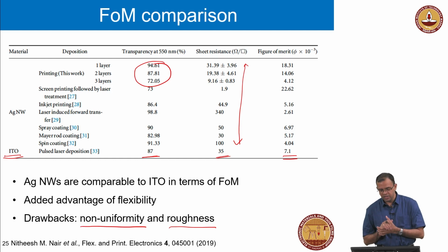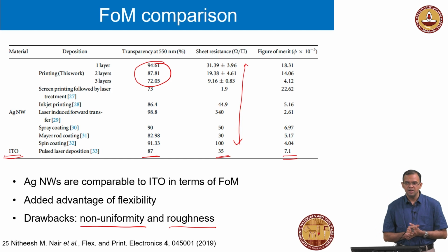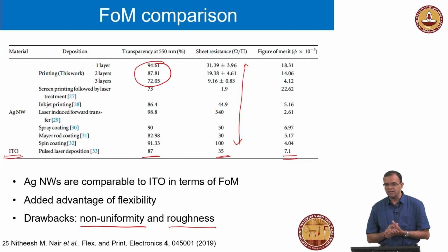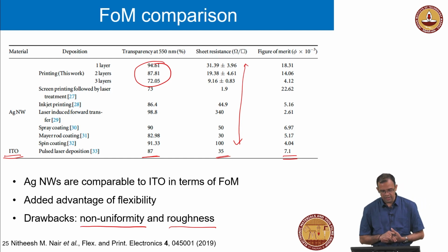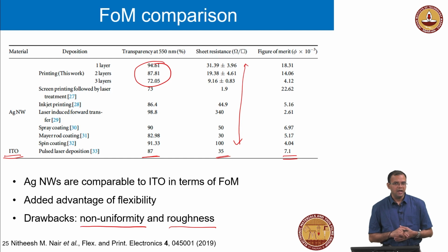So again we are looking at, can we make composites so that the overall composite film has lower roughness, and what sort of roughness values we can achieve, those are challenges. But essentially if you can tackle some of these challenges, it is possible to actually have silver nanowires as an alternate layer to ITO. And interestingly, it has not been done.